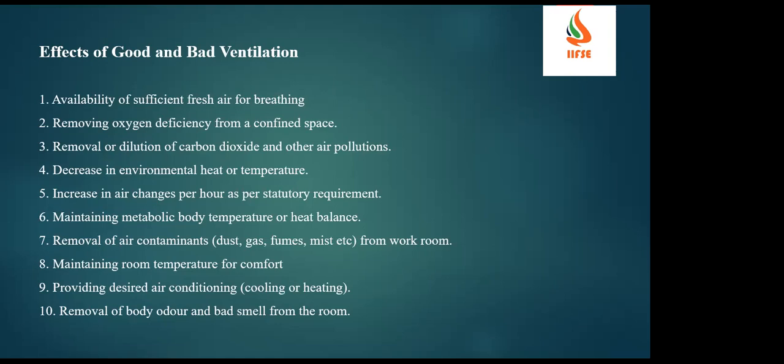First is availability of sufficient fresh air. If we have a proper ventilation system, what will happen? Automatically, you will have sufficient fresh air. Then automatically what will happen? Removing oxygen deficiency from the confined spaces. For example, in confined spaces, you are giving a ventilation hood for the people who have entered inside, so that there will be removal of oxygen deficiency.